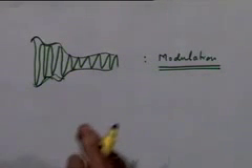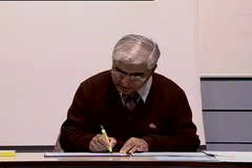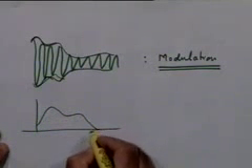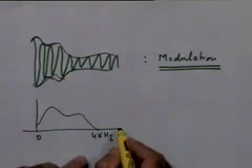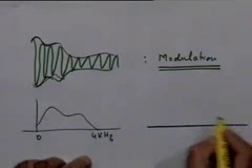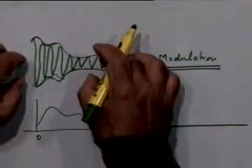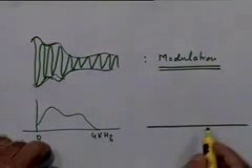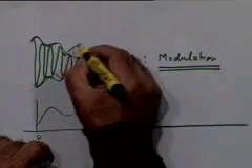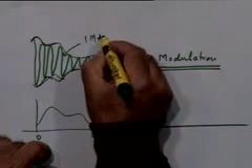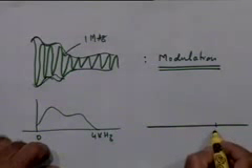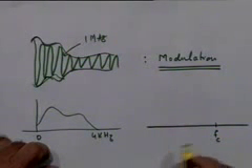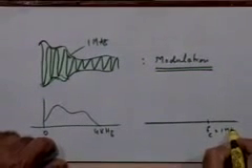Modulation helps me to translate the spectrum of the signal which was earlier lying in the band from let's say 0 to 4 kilohertz, right? Where does the spectrum translate to now? What is the spectral occupancy of this signal? Let's say this carrier I choose as 1 megahertz, right? It's a carrier frequency of 1 megahertz, so the center frequency of this will be around 1 megahertz, right?